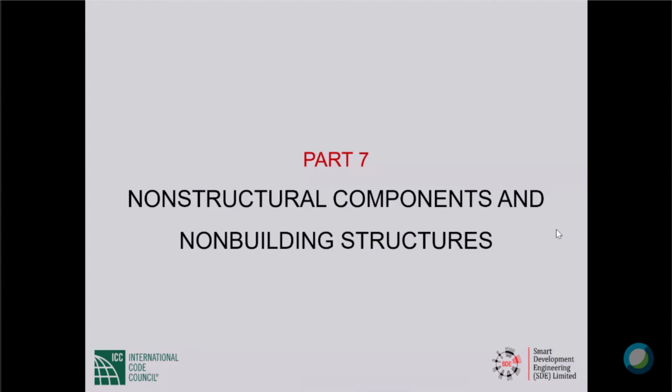This is a three-part question. Which load case and or combination shall be considered for checking drift? Which load combination will be considered for checking drift? The real answer is that unless you have a very unsymmetrical building, gravity loads do not cause significant lateral deflection. So the drift that we are talking about is caused by the earthquake forces or wind forces.